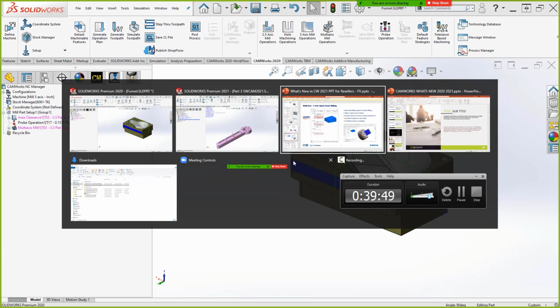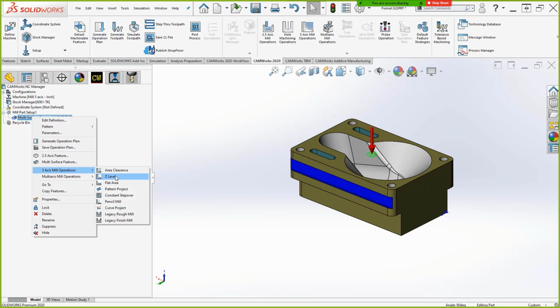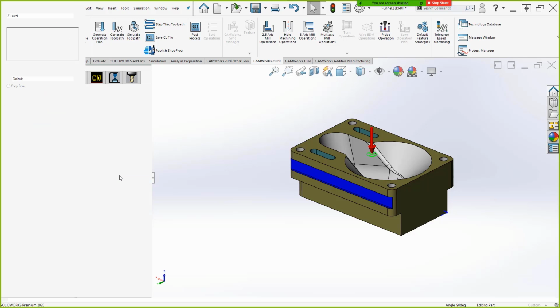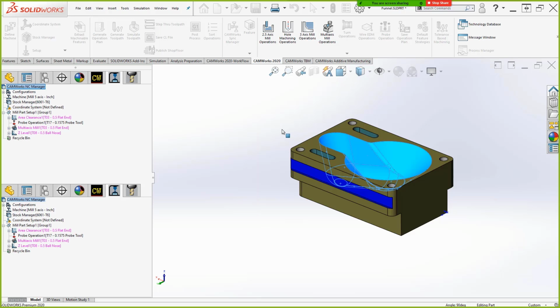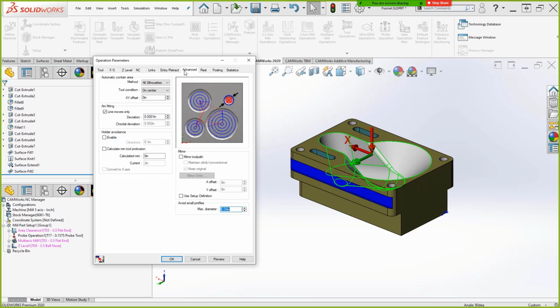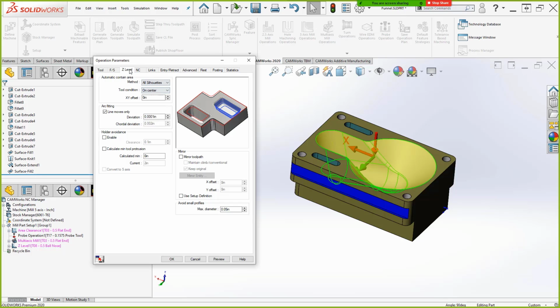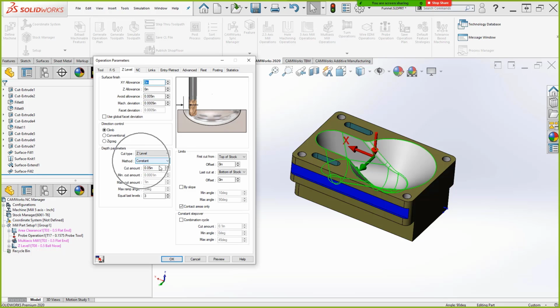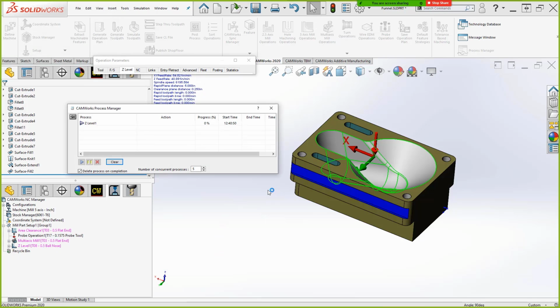And what was I going to show you that I already forgot about? Spiral milling. So even with SOLIDWORKS CAM, our base level option, we only have the Z level finishing pass when it comes to multi-surface features. So I'm going to add that real quick just to show you this spiral idea. We're going to be smart. We're going to jump over here and say all silhouettes, making sure it's not going everywhere. Let's head over to Z level, and right now we're on constant. Let's bump up our cut amount in the interest of generating code quicker. This would not be a very good surface finish, but I just want toolpath to show up quick.